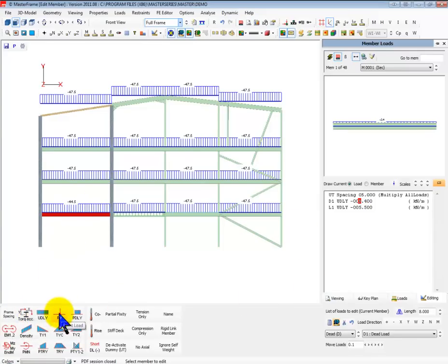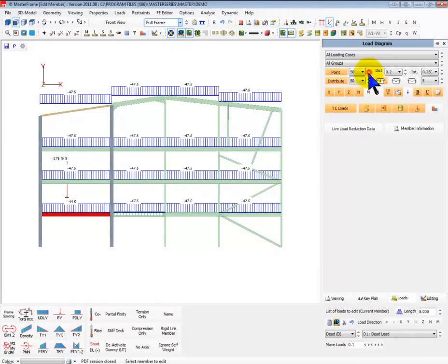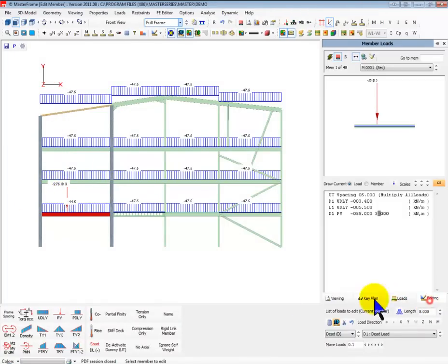But we can put additional loads on. We can add in a point load, for example, of 55 at 3 meters. There it goes. And we just need to scale the point load down a wee bit in our diagrams. If I go to this, I can pull that back down so it's not looking as astronomical, and back into my editor. We can put partial UDLs on.